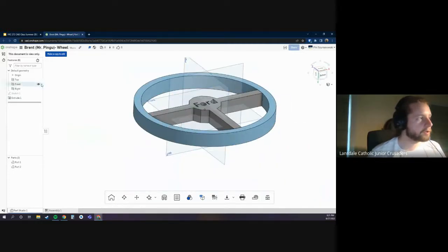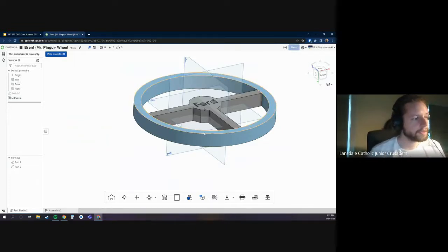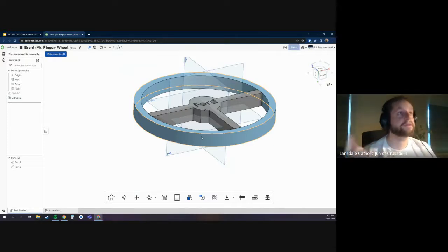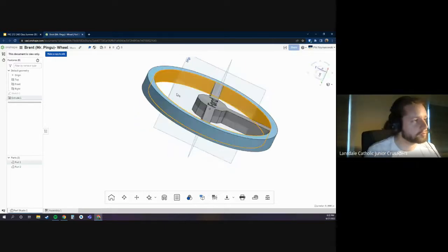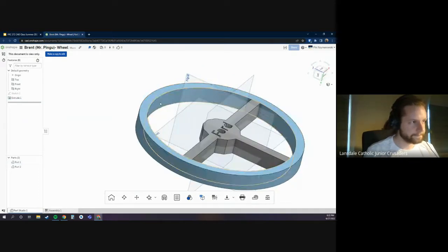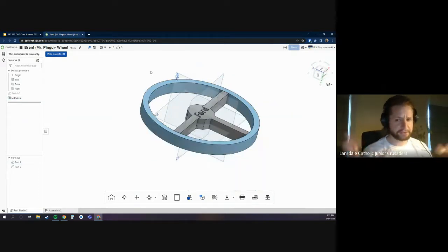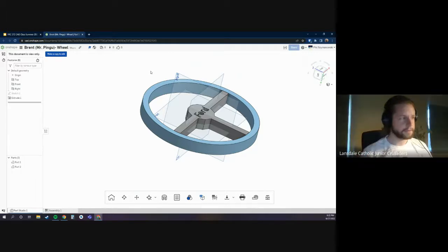And then you can use a revolve that uses an intersect. What that does is it will only keep the material that intersects with your new revolve. It'll subtract everything else away. And now you're left with a ring that's round instead of a ring that's kind of squared off, like a cylinder. Does that make some amount of sense? A little bit of sense? Some amount, yeah. All right.